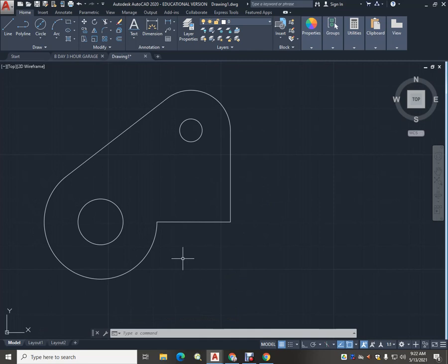Yes, there is. So this one actually says that we have to use the fillet command, and our dimension then says that we have 2 fillets of 0.25 to consider on this part. So the 2 fillets, one comes in here, one comes in here. So let's grab the fillet command.